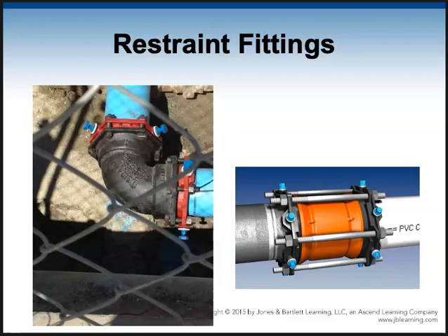So that's how they hold the plumbing together. And as you can see, in all of this underground plumbing these days, they're using heavy-duty PVC pipe. The pipe has to be of a certain kind and a certain thickness, and all of that is laid out in the standards in NFPA 24.